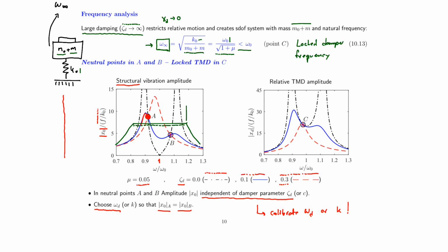And this, of course, we would bring down as much as is needed to stay below maybe fatigue limits or comfort limits for our pedestrian bridge. For the blue curve, point B satisfies this condition, but for point A, we have a peak that is above. So it's like a waterbed, if you remember that. If you push down at one point, it will go up at another point. And the question is, of course, to find the optimal balance.